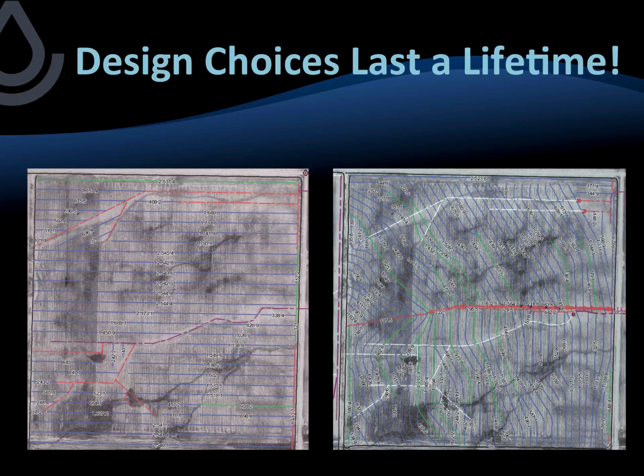These are the designs for the field that we just saw in the aerial shot. On the left was the design, the traditional design that was going to be implemented, with laterals more or less going up and down the slopes of the field. And the design on the right is the drainage water management design. You'll notice that these laterals, indicated with the blue and green colors, are located on the contours. The contour lines are not shown here. So there's no opportunity to manage this field on the left if this design had been implemented. And the field on the right has drainage water management capability.